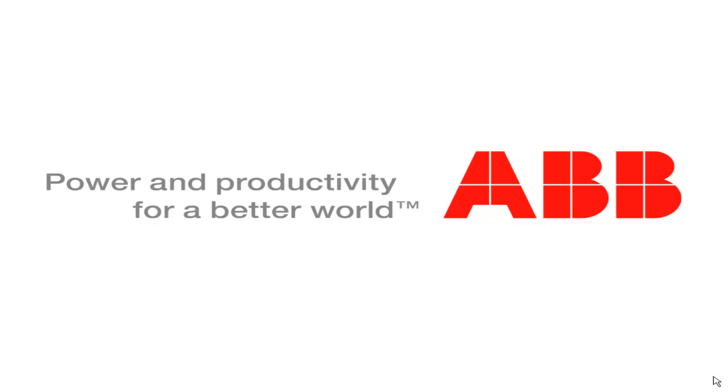My name is Adewale from Osamad. I just want a bit of clarification on whether you put into consideration the effect of temperature on the efficiency of the electrocoagulation process. For electrocoagulation, on the majority of applications that we've worked on, temperature doesn't seem to have much of an effect. It's only when you start using more specialist DSAs, dimensionally stable alloy plates, for certain electro-oxidation systems, that we notice that an operating temperature above 30 degrees is a bit detrimental.